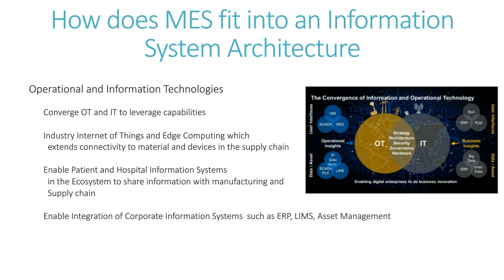I'll give you one example that I think is extremely relevant, which is networking. When I started doing this type of work many, many years ago, Ethernet and networks were non-existent on the factory floor. We started putting them in and connecting them into the corporate backbone. We had to do that with certain technology to isolate and make sure that we had information integrity, but not creating problems on the corporate network. But using Ethernet technology nowadays is almost a no-brainer. Everybody knows that they have that, and we have wireless.